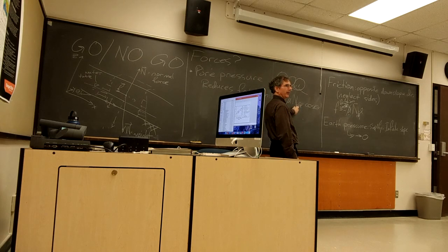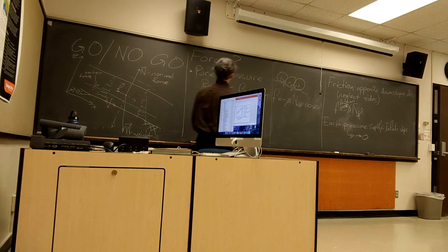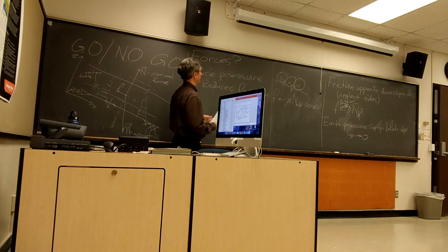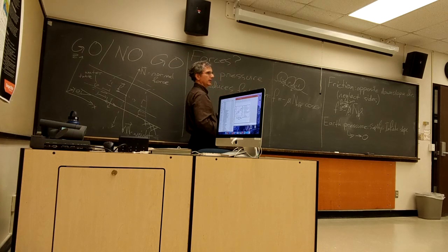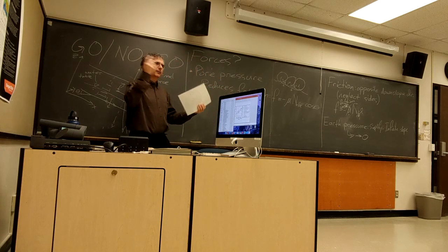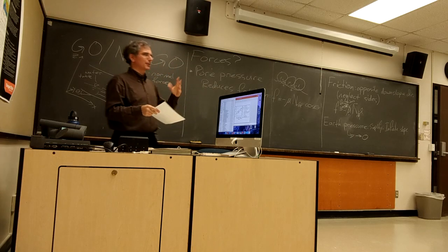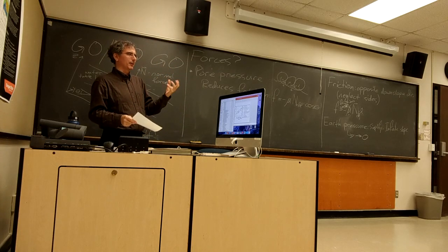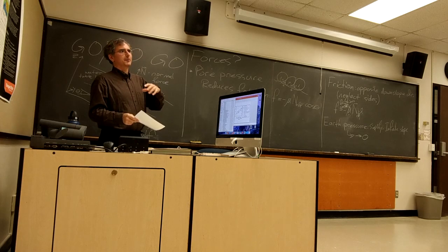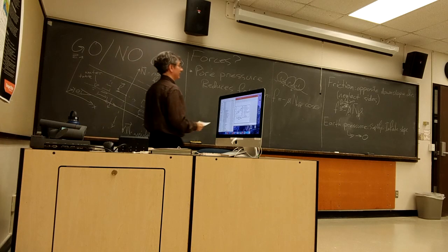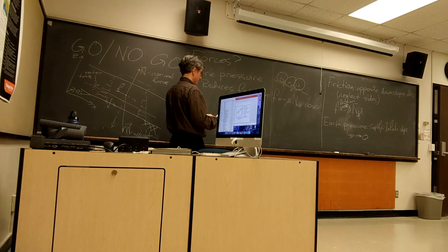All right, so I'm going to wait a minute before I try to write down what this effective normal force is, until we dispense with forces and start talking about stresses. But essentially, the effective normal force is the normal force minus the pore pressure, except we never really say it that way, because you can't subtract a pressure from a force. So when we talk about normal stresses, then we can subtract pressure.